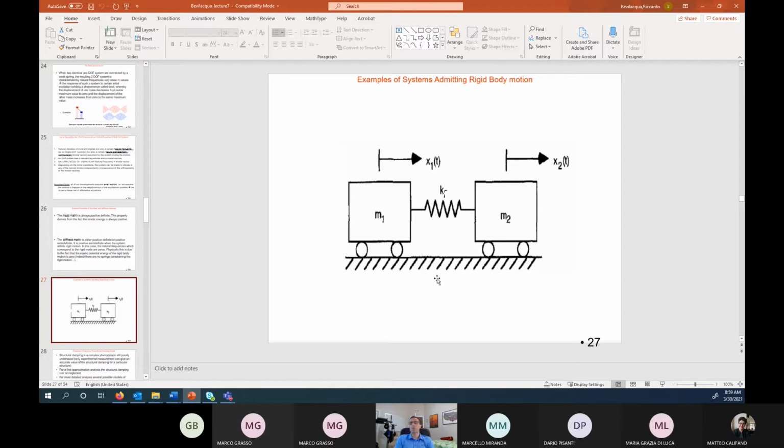And that's what you would find if you've ever used SolidWorks and other software tools that compute for you, for a continuum, a finite element analysis. We'll see what that means. And they compute the natural frequencies and modes for your system. If your system is unconstrained, so if it's just a spacecraft, for example, free floating, not constrained to anything else, it will give you some 0 frequencies because the system can undergo rigid motion.